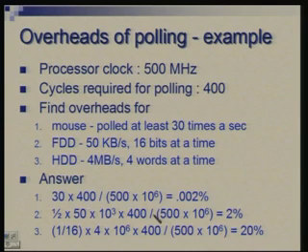And again similar factors, 400 cycles lost every time you poll, divide by the processor clock, we have 2%. That means only 2% of the cycles are dedicated for this. So, this is not as comfortable as the mouse, but still tolerable. The only problem is if we had several of such devices, then these percentages would add up and we would have lost sufficient time. But let us say this in isolation, it is still a tolerable device if you do not have too much of other activity.